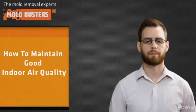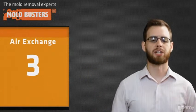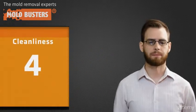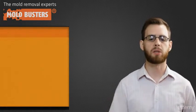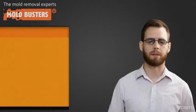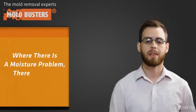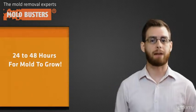Several factors play a role in the maintenance of good indoor air quality. 1. Moisture control. 2. Proper ventilation. 3. Air exchange. And 4. Cleanliness. Now, moisture control is eliminating and repairing sources of moisture to reduce relative humidity inside of the home. See, mold thrives in damp environments. Wherever there is a moisture problem, there is likely a mold problem. It takes around 24 to 48 hours for mold to multiply after a water intrusion.